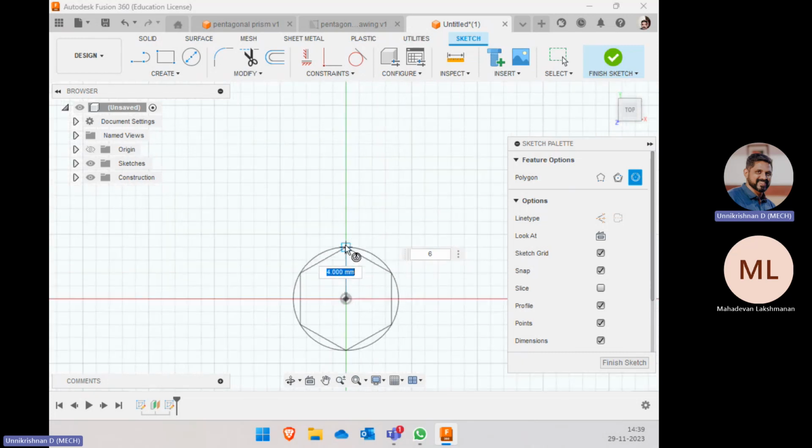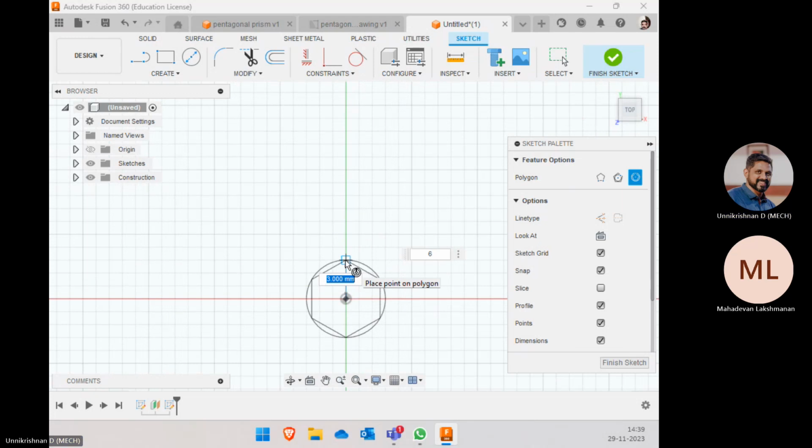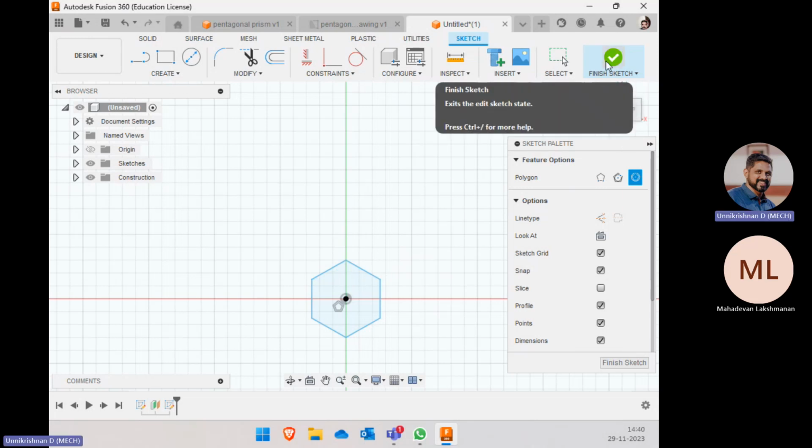It should be considerably small, but at the same time, you should understand there must be filleting curves possible. What is the fillet curve generated for this thing? The radius is generally the thickness of the plate. If you're taking 1 mm thickness, the fillet curve should have 1 mm. So if I am going to give 3 mm here, that means 1 mm on this side and 1 mm on this side should be possible, right? Can be possible, right?